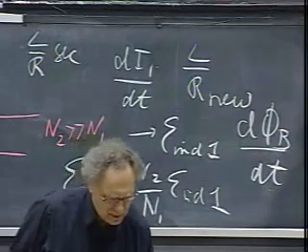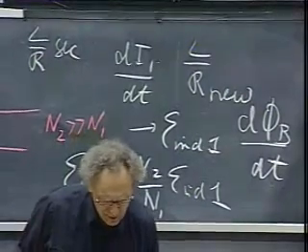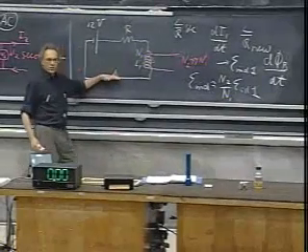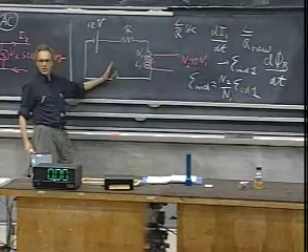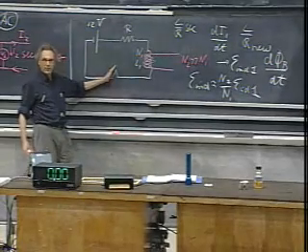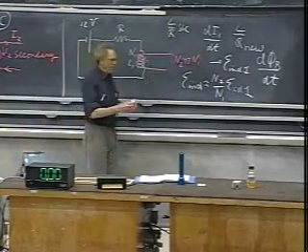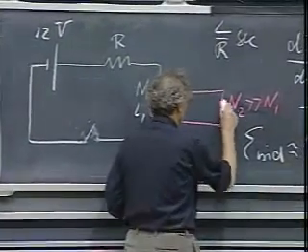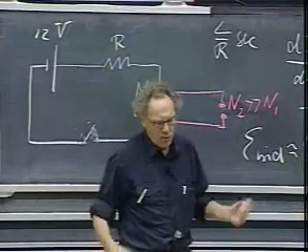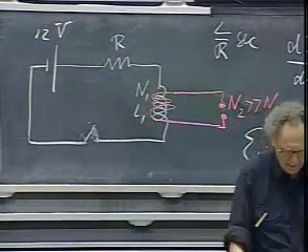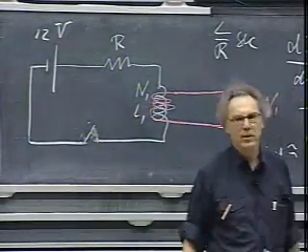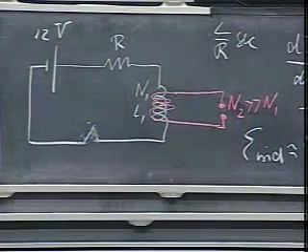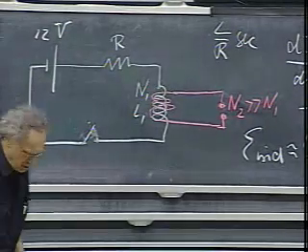And so what is happening with your car, without you realizing it, there is a circuit that closes and opens and closes and opens and closes and opens. And it's only when you open it that you get this pathetic high voltage here and that the spark flies over. And if you run your engine at 3,000 RPM and you have a 4-cylinder, that happens 200 times per second. But it is the breaking that does it.